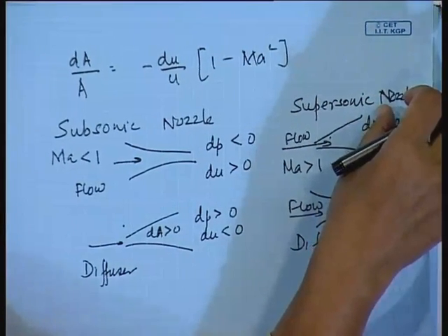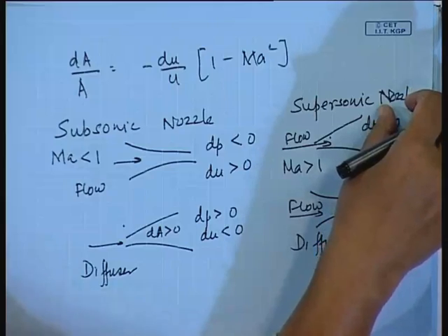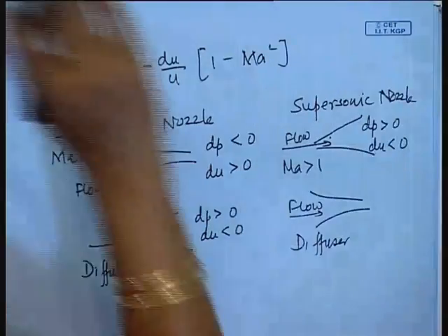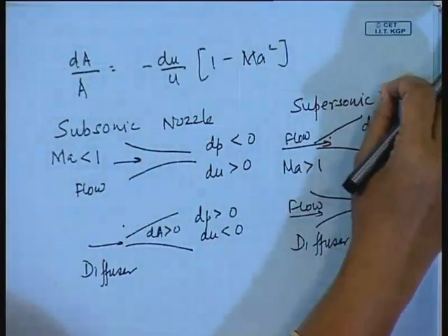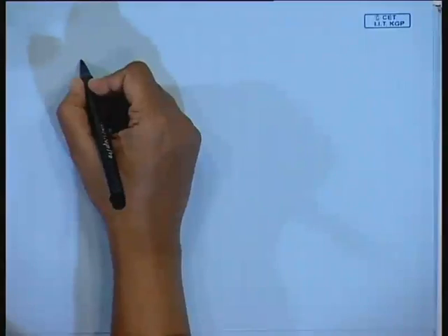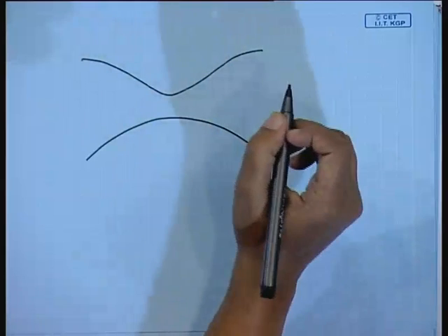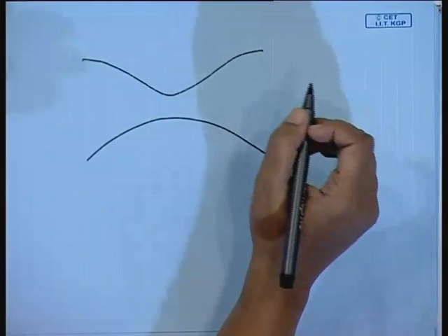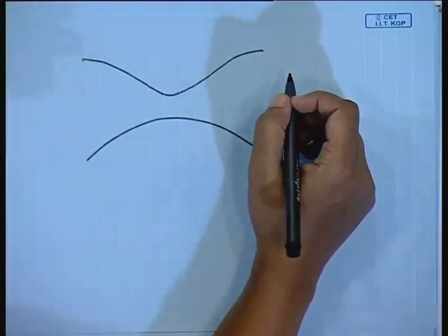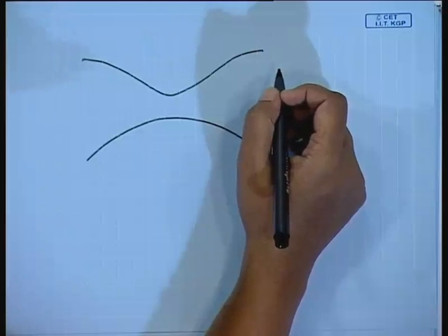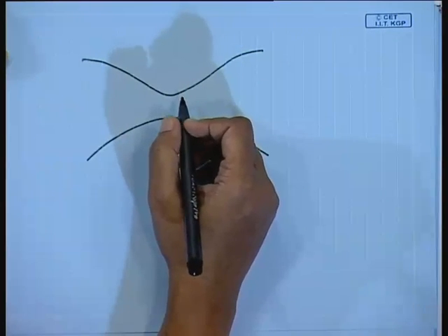So, for that particular case, if we start from a very low velocity and have to go to the supersonic range, what do we need? We have to use a convergent divergent nozzle, otherwise it is not possible. We have to do something of this sort, if we want to obtain a supersonic stream starting from very low speeds at the inlet.